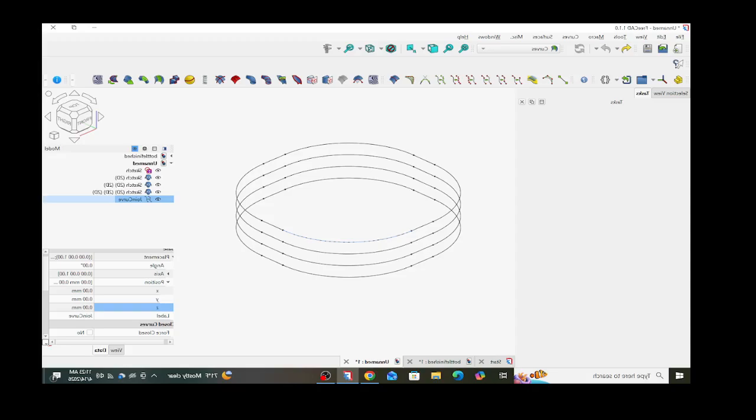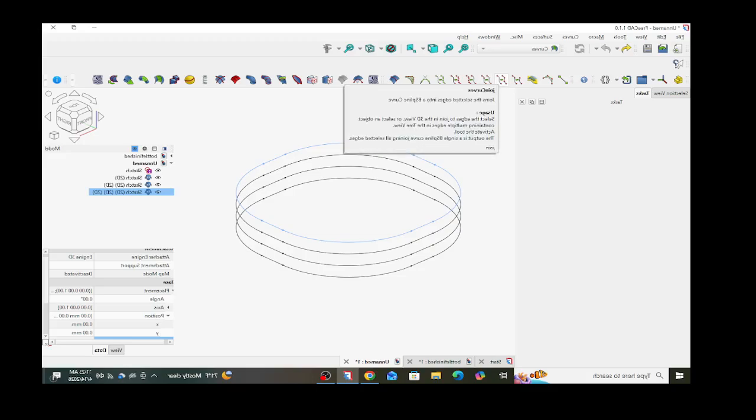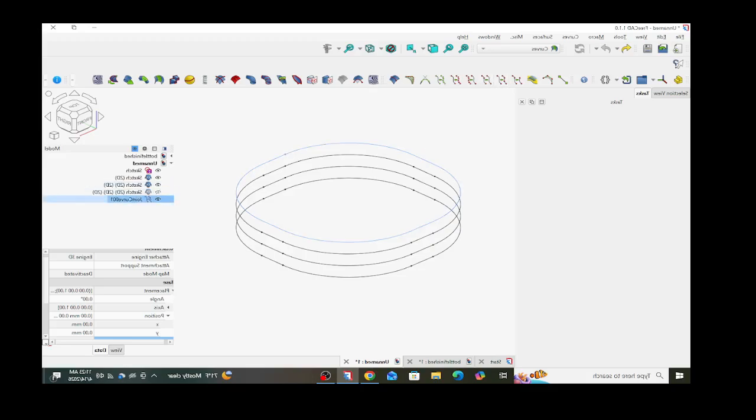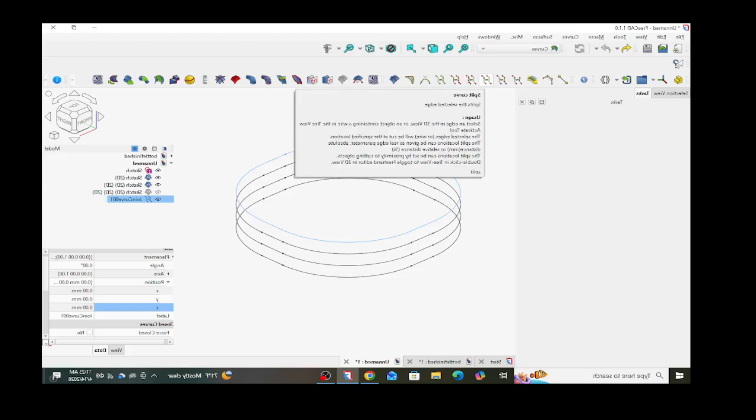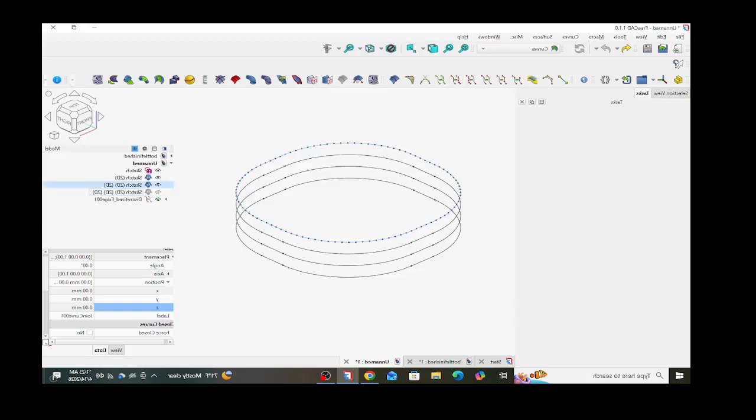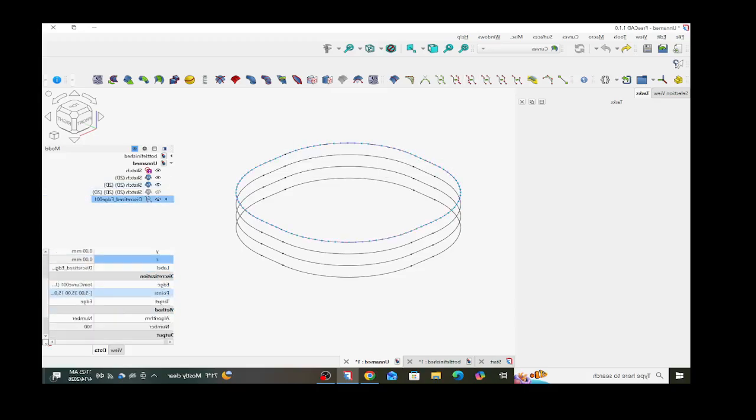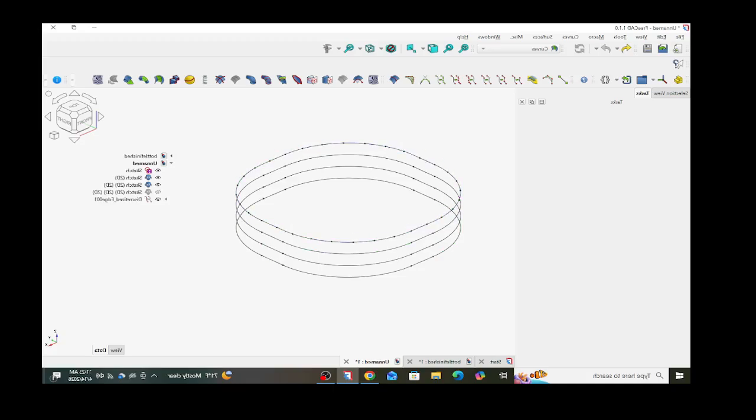It didn't quite work out. Click on it in the tree view, so select the whole sketch and click join curve. There, now we have a join curve that's one solid wire going all the way around. We're going to discretize that join curve a total of 32 times because there's 16 flutes going around the top of the bottle.